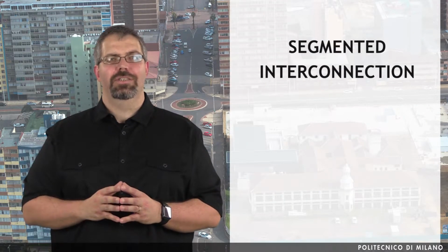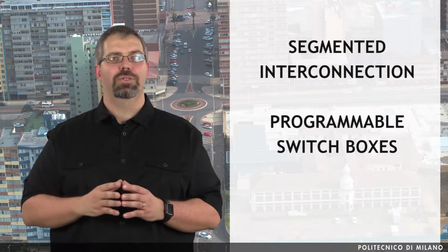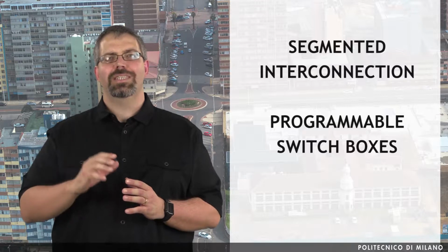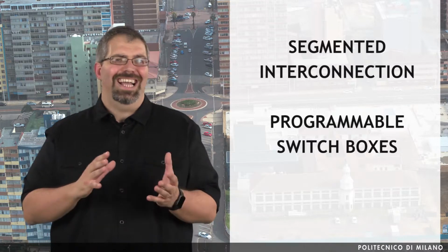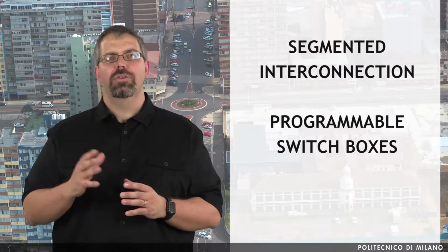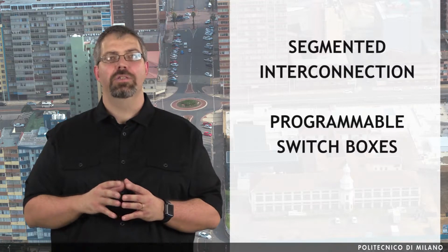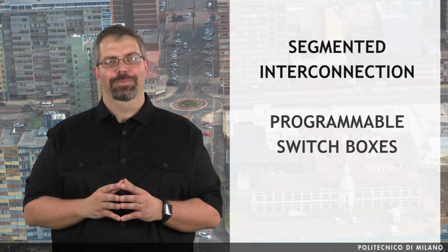Segmented interconnection is based on lines that can be interconnected using programmable switch boxes. Also, in this kind of interconnection, there are lines that cross the entire device in order to maximize the speed of communication and limit the signal skew.